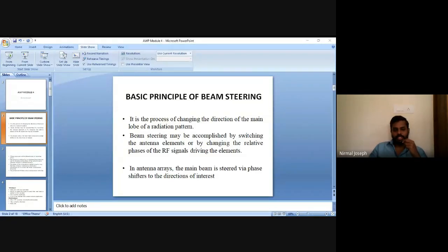In the RC phase shift oscillator, the phase shift part we are doing like this only. Just by introducing a network of capacitors and resistors, we can achieve the phase shift. So a phase shifter we can achieve just by using the resistor and capacitor. A transistor will have a 180 degree phase shift, so we can just use a transistor for the 180 degree phase shift.